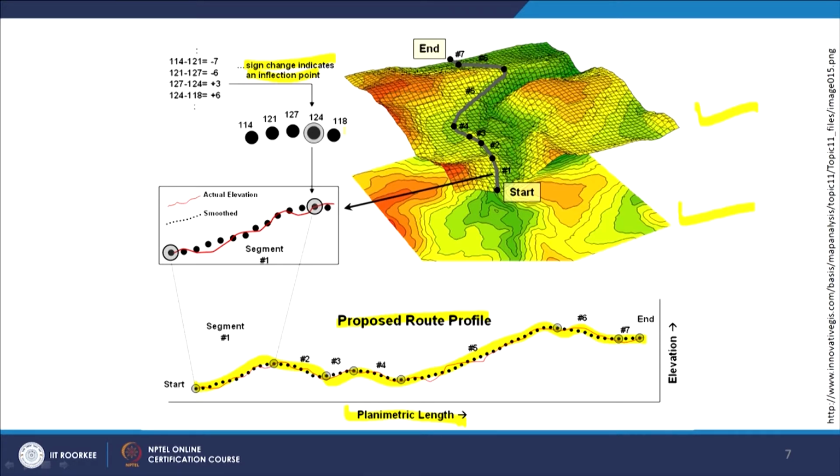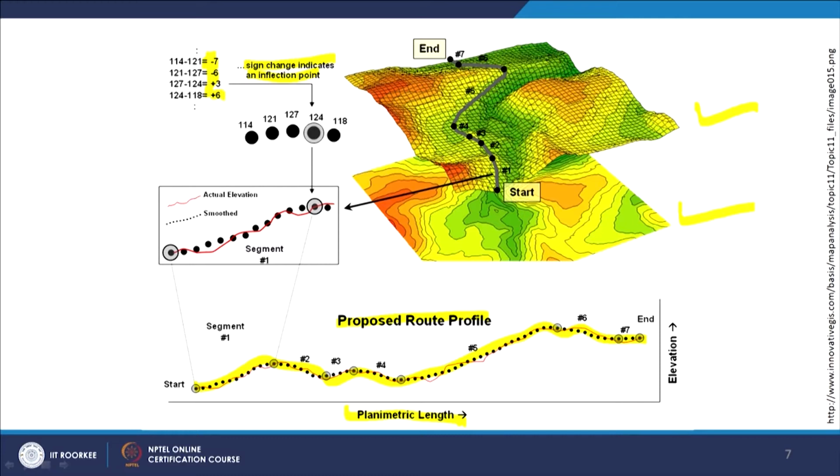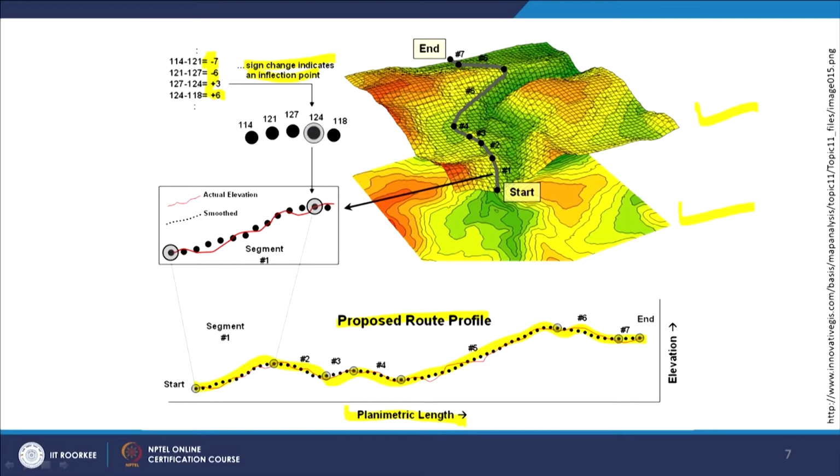Now, here these values will tell us where it has to be climbed or where it has to go down if it is just a simple road. But if it is decided that I want a continuous smooth road without much up and down, then by looking at these values I would know what kind of plus or minus. Plus means it is convex, minus means concave, and if I want to make the road flat along this proposed line, then I should know where the filling will be required and where cutting would be required. That analysis can also be done in cut and fill analysis, and more accurately there, but here we would know where things are required. There also you can, which we will be discussing a little later about cut and fill analysis.